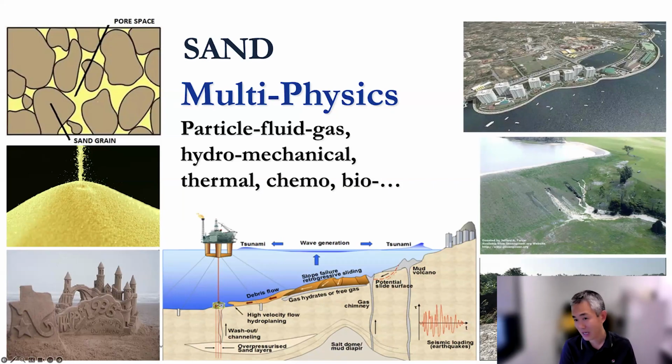Also in dam engineering, especially in earth embankment dams, we need to pay a lot of attention to the piping phenomenon. Small pipes develop, and at a certain hydraulic gradient, small soil particles can be carried out through the big pores. When more fine particles are carried out, the pipe can be enlarged, and then make the whole embankment dam collapse.